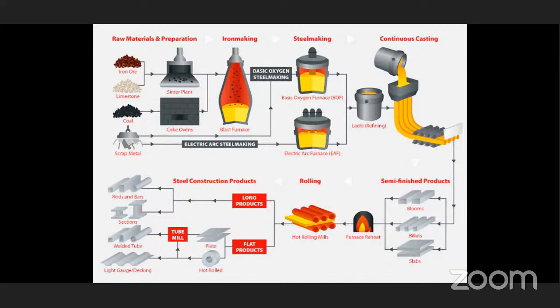So what is meant by basic steel making? The basic process is used to remove sulfur and phosphorus besides the other impurities. In this case the furnace lining in contact with the slag is made of basic refractory materials such as dolomite or magnesite. Then we can say this is a basic steel making method.